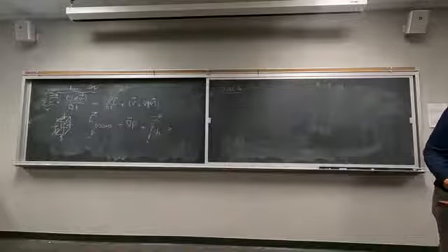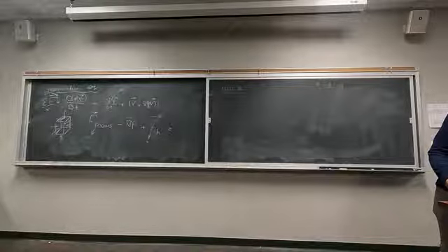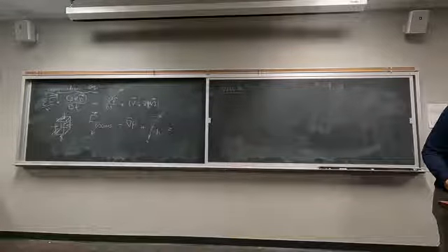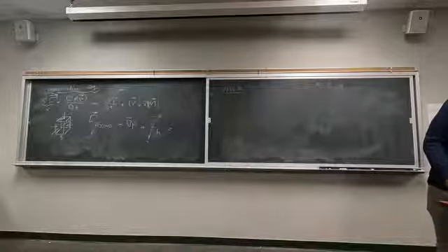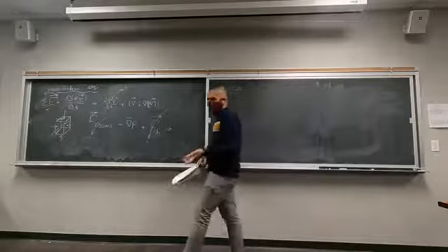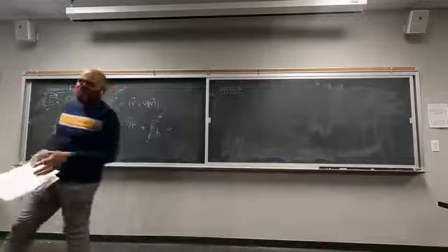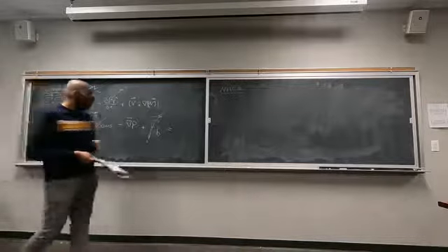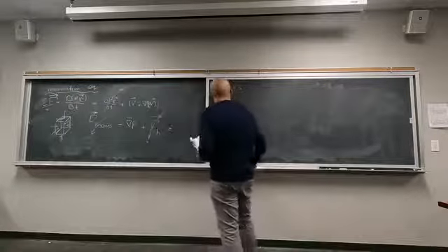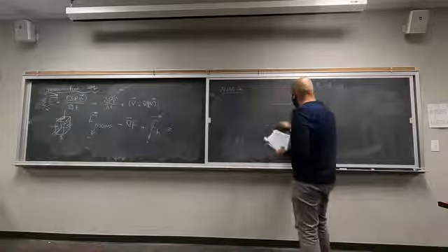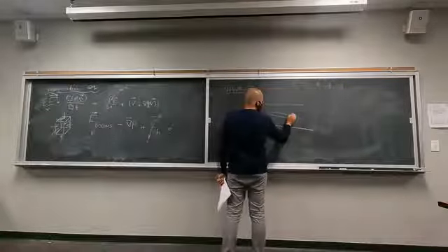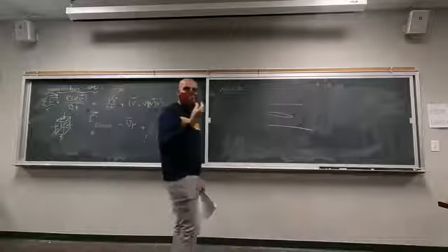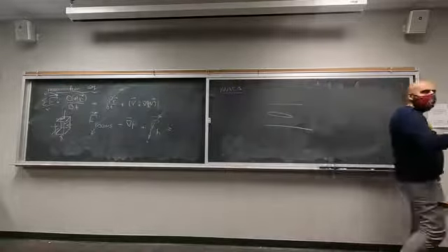But one thing that I want you to understand here is the fact that this momentum equation is a three-dimensional equation. It essentially means that this equation is three different equations, right? So the NASA engineers had to come up with a way to simplify this a little bit because they wanted a simple equation. It's not actually that simple, but the simplest equation possible to calculate drag. Okay. So what they did was this. Let's say this is the wind tunnel. The first thing they did was to change the angle of attack, make very small changes in the angle of attack. And also, they started with thin airfoils.